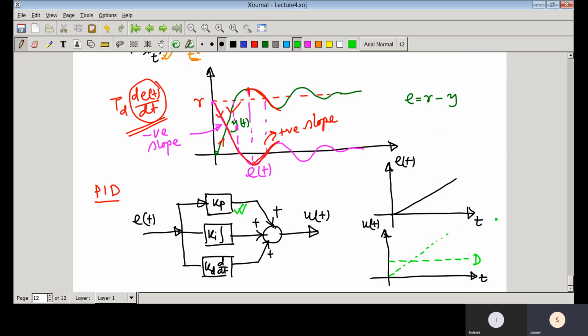And what would be your integral part? Integral part is Ki integration tau d tau, so that means that would be tau square. So here you can see that this particular action is PD action, this is only P action, and the PID action is the parabolic one. So whenever you use proportional, integral and derivative, that is actually the control input that you would have.